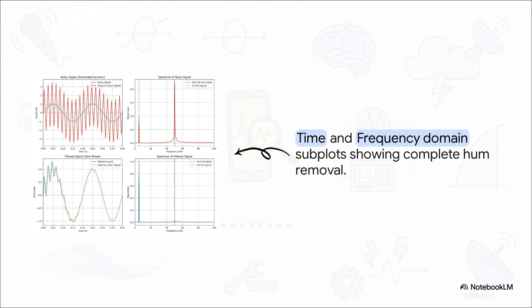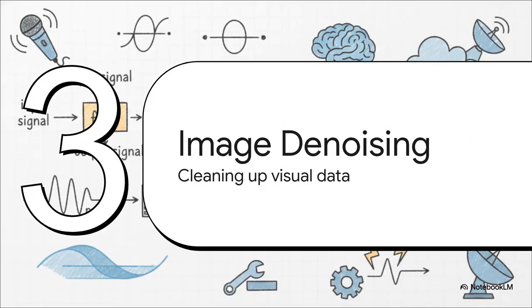Now, observe the post-filter spectrum down at the bottom right. That 50 Hz skyscraper, it has been entirely vaporized. There is nothing left but a tiny, almost imperceptible notch in its place. And as a direct result of that precision strike, check out the filtered time domain plot on the bottom left. Our solid blue line now perfectly, flawlessly tracks the dashed orange original signal. The 50 Hz electrical interference is totally gone, and thanks to our zero-phase filtering, there is absolutely zero temporal distortion. It's a perfect cleanup.